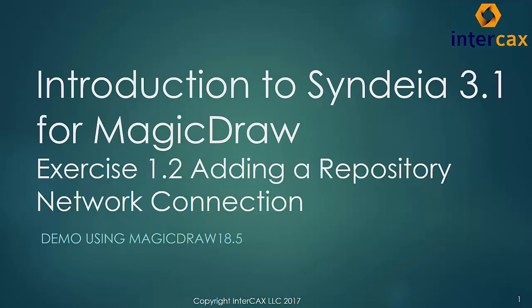Before we can create connections to an external model, we need to enter the access information that enables us to connect to the repository in which the model is stored. We will call that a repository connection, as opposed to the model connections between model elements that Syndeia will create later. The objective of this video is to show how to set up repository connections, either to a configuration-managed repository or simply to a folder in your local file system.